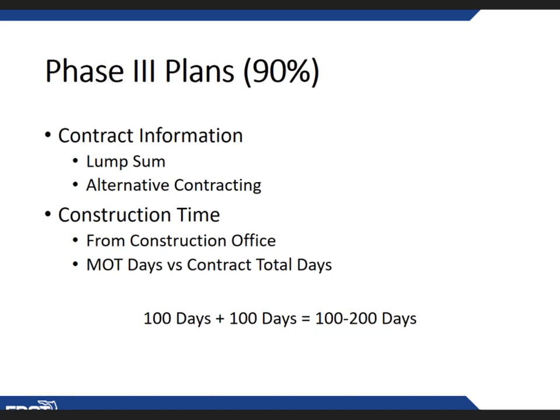But if that second project cannot even begin, or the work is such that all the earthwork, all of the resurfacing, just adds on the additional number of days, you could go up to and including that full doubling of the total number of days. But never should you blindly just add those 2 projects.